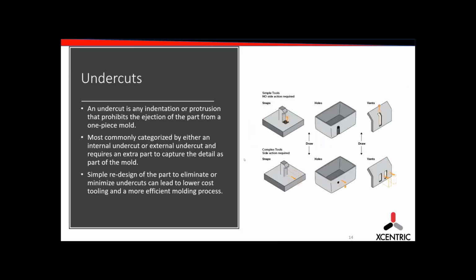I mean, usually it's lifters. If you have internal, say you're going to capture this hole from the interior of the part, you would end up with a lifter. If you're going to capture it from the exterior of the part, then it would be a slide. So anything on the outside of the part typically is a slide. Internal undercuts are created by lifters in the automated setting.